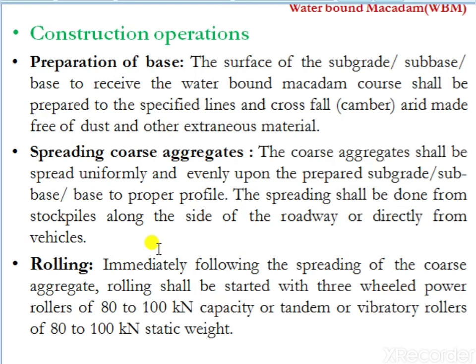So the coarse aggregate should be spread uniformly and evenly, and this spreading can be done manually or using vehicles.